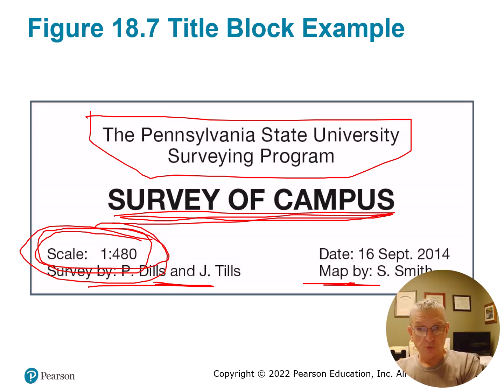And what that means is 1 English inch on that drawing surface when plotted at scale is equal to 40 feet on the ground. So if you scale something that's 5 inches long on the paper, then it's going to be 200 feet long on the ground. So a 200 foot long building would be 5 inches long on a 1 inch equals 40 foot scale map.